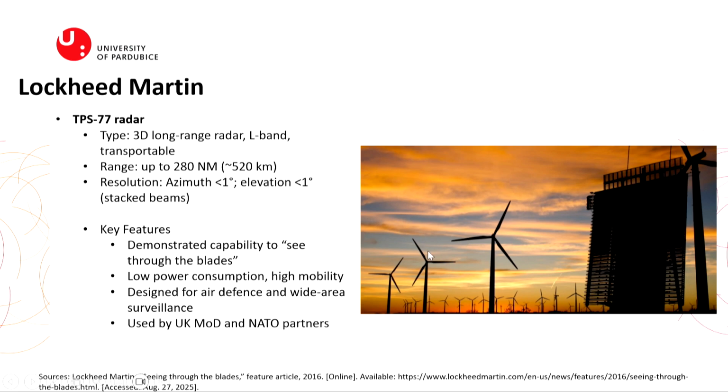So this masking after wind turbines is not huge. The problem is in the exact place where the wind turbine is. If you expect that the rotation speed will be very high, then the radar doesn't see anything until this wind turbine, and now it can see relatively easily. It doesn't see about 2-3 range resolution cells so well, but after this it can see everything, because imagine this is not solid, it is just 3 blades.